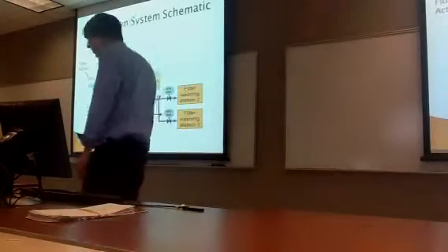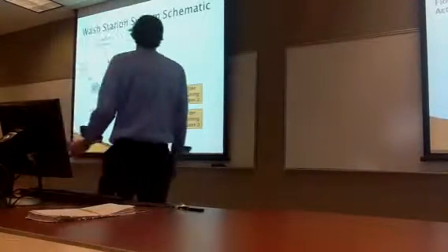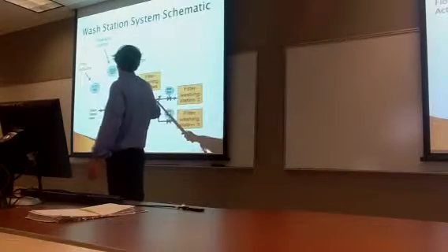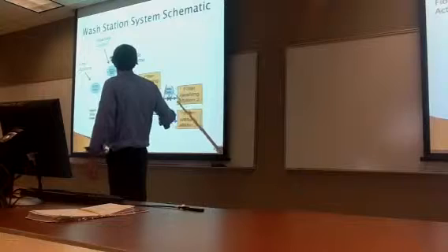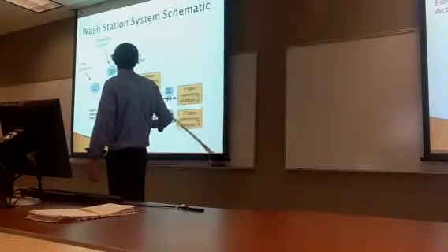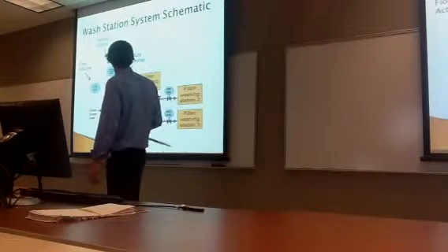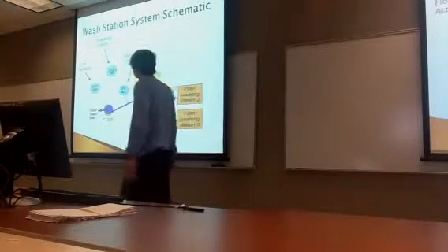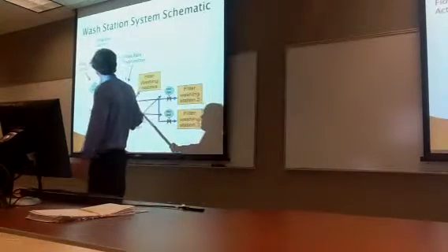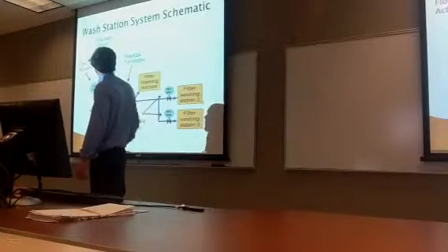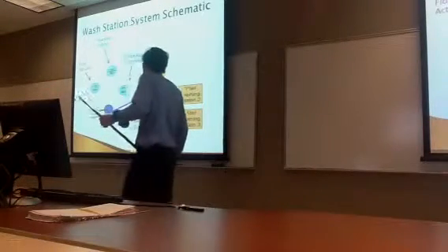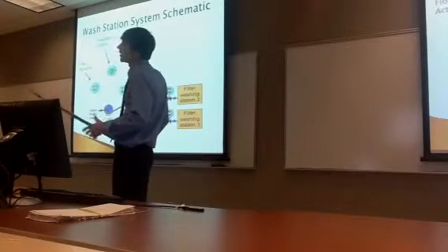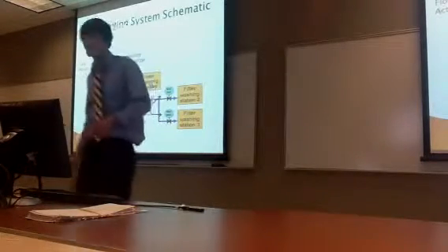This is a schematic of the wash system. You see here, water is pumped, it goes through this system, and you see the 2 valves here which allow you to run whatever number of stations you need to, and in our case both valves are open. This is the flow control, where the flow rate transmitter reads the flow rate, which then tells the controller to tell the actuator whether to speed up, slow down, or remain the same.